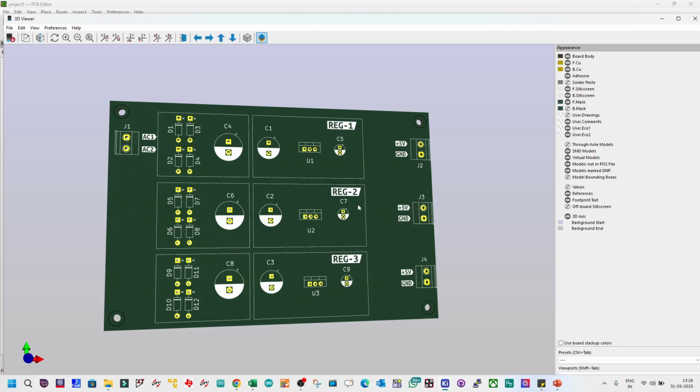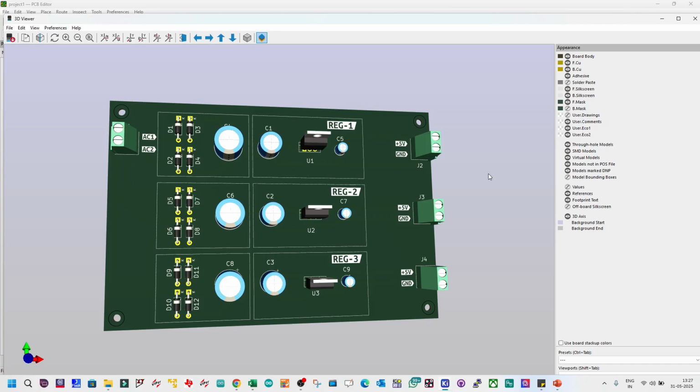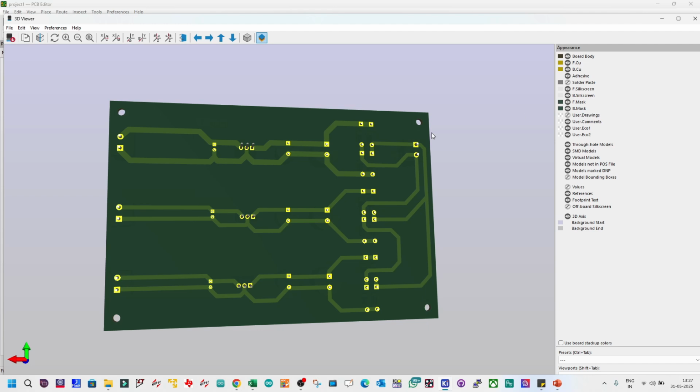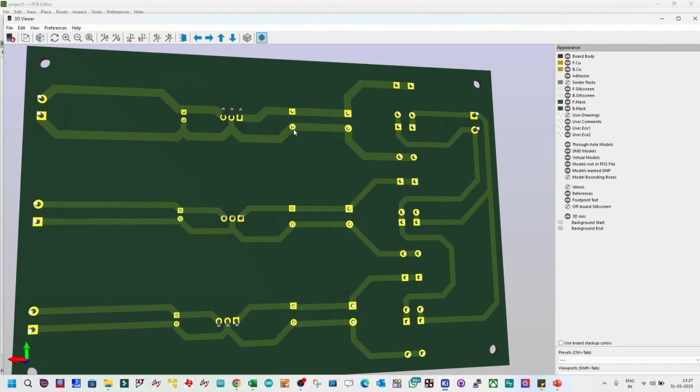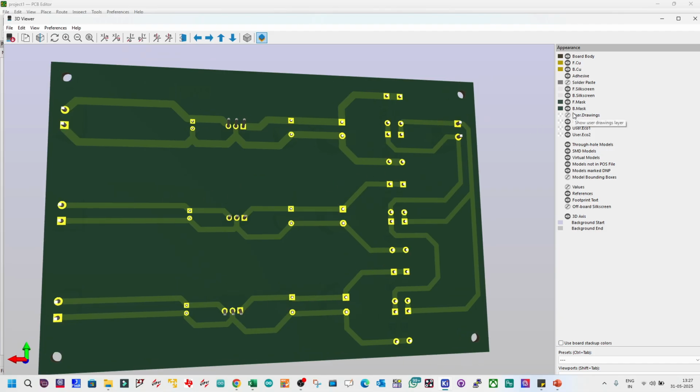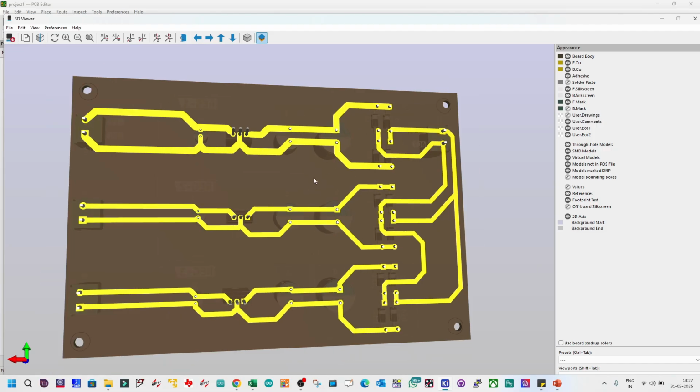Yeah, tomorrow our plan is maybe we need symbol creation as well. So far, our layout completes. If you want to review the backside of routing, you can do this, and with the backside mask it will look like this. Wherever you see yellow color, that is the soldering spot. Those are the masks open for soldering. But if you want to see the routing, you can remove the mask. There is no mask, so now everything is exposed. Exposed means you're able to see the actual routing, the copper on the bottom side.